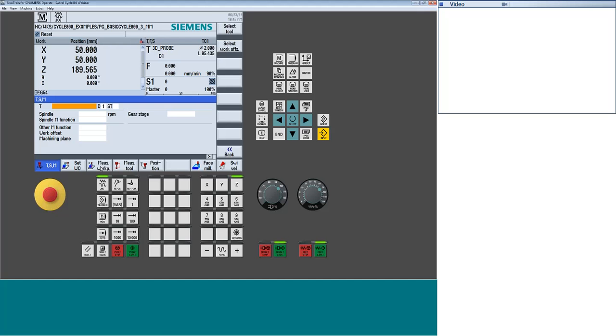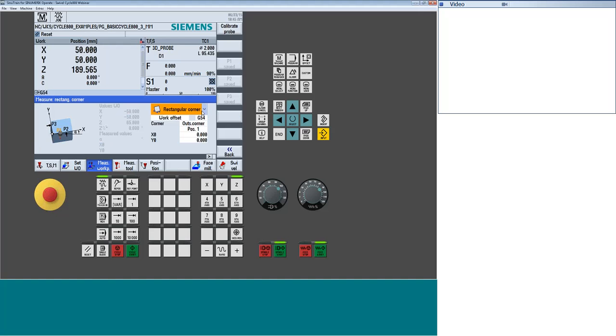Well, we're going to use a feature called, and I'll pull it up right here, Align Plane. And what Align Plane does is allow us to first align our initial datum surface. The way this works is you're simply going to have the machine sitting typically at its base 0 location. So I don't want any offsets compounded.